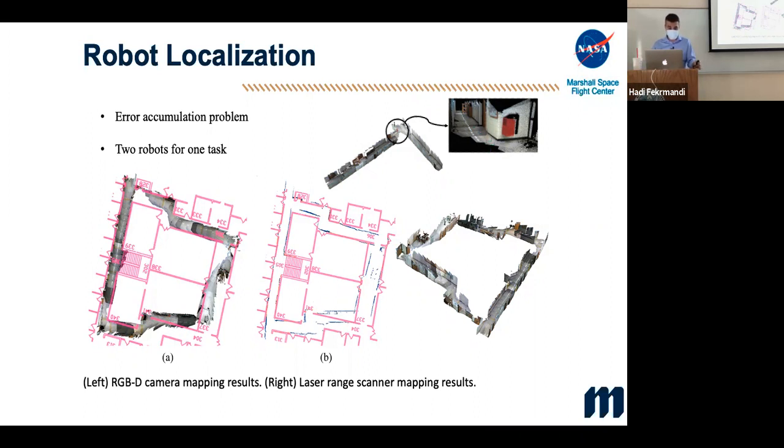Once you look at the image here, you can see the map that is generated. Where it starts in the corner and goes, the error accumulation is visible. The map is deviating from the corridor. It is very accurate, but as you continue, this relative state estimation adds up. If there was slipping because of a sandy area, that error coming from the locomotion would also be added. But still, it is very useful.